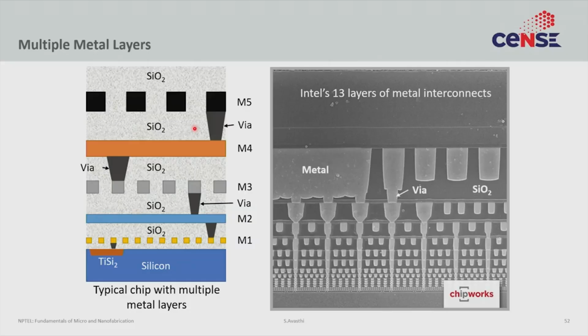And the last point is that we discussed the term back end of the line processing, but we did not go into detail of what that means. This is back end processing. All these silicon dioxide depositions would be considered back end because they are being done with metal on it, which means you cannot do a lot of the RCA cleans that we have discussed. So you have to do a lot more gentler cleans that allow metal to be used.